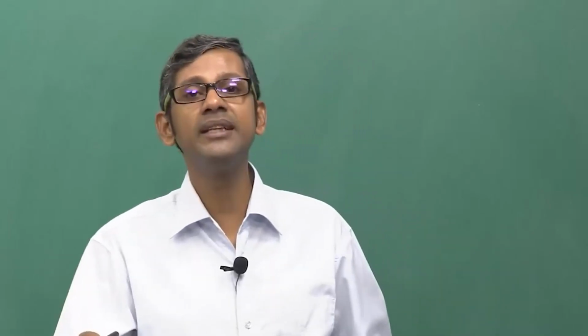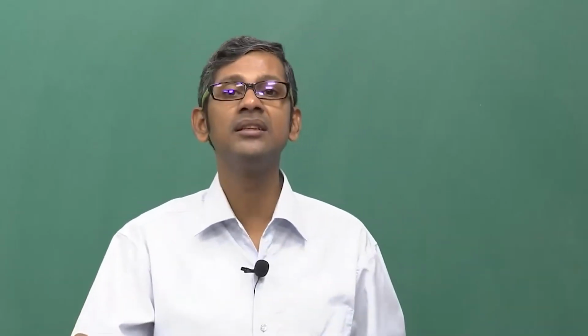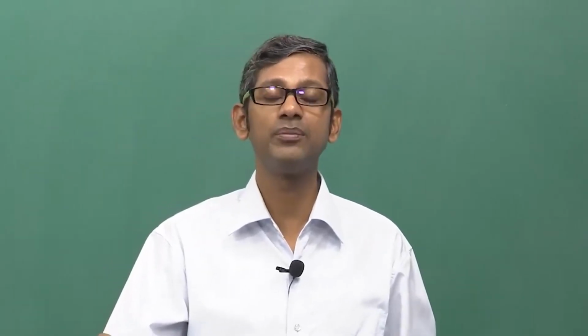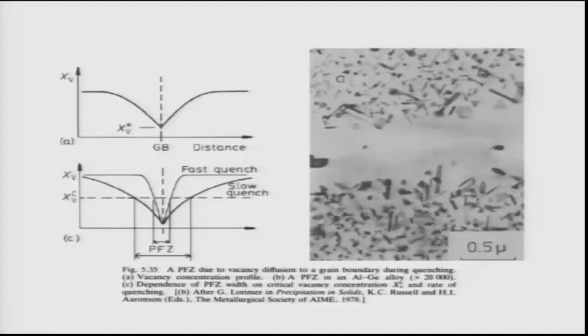But the most important thing they allow is the diffusion of the copper atoms, because diffusion normally happens in substitutional solid solutions by vacancy movement. So the vacancies are actually present in large number during aging treatments. This allows diffusion to be faster. That is one important aspect. As I told you, diffusion has a sink. Dislocations will act as a sink for the diffusion, because the vacancies will form a loop, and this can again lead to the formation of dislocations.